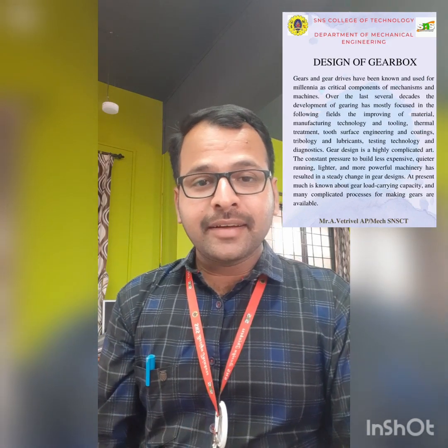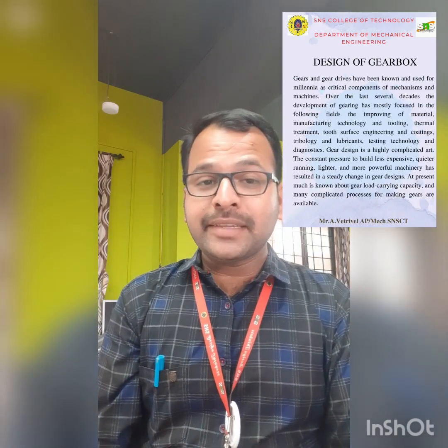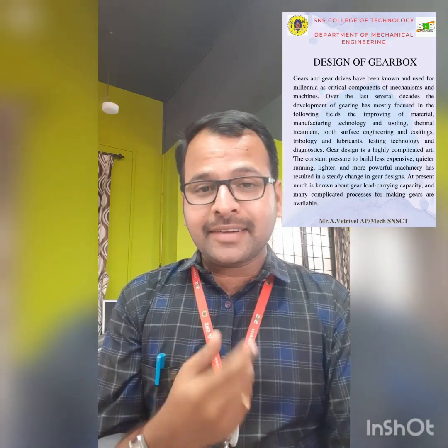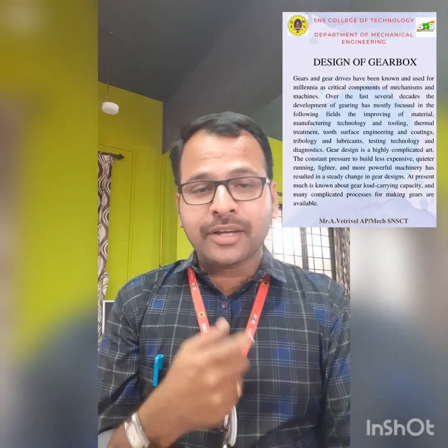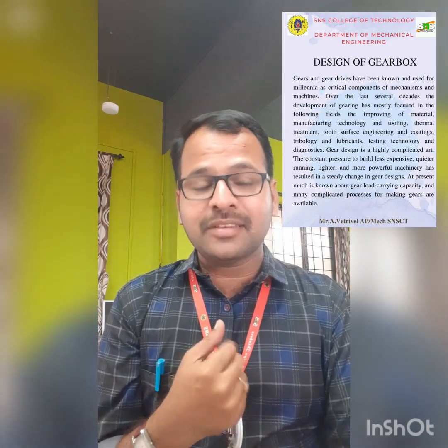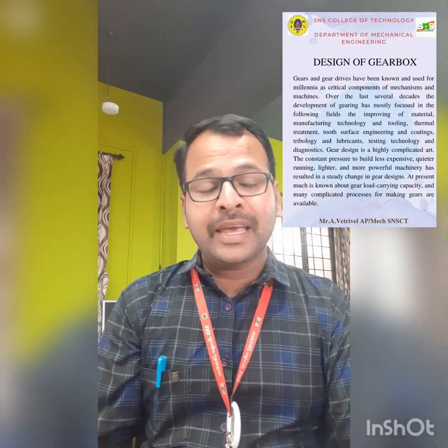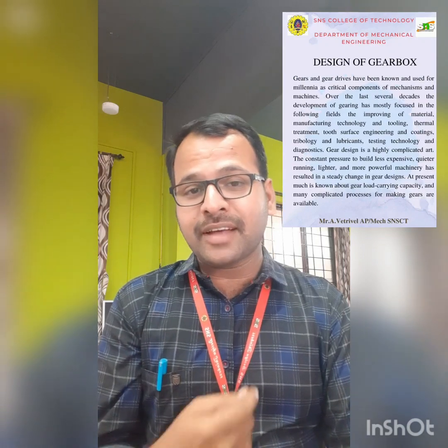For making the gearbox design, there are a few things we want to remember. Initially, to obtain the basic size of the gearbox, the nominal torque at the output of the speed is calculated by using the observed torque at the driven mechanism or machine, or the prime mover torque multiplied by the gearbox ratio, if the observed torque is unknown.